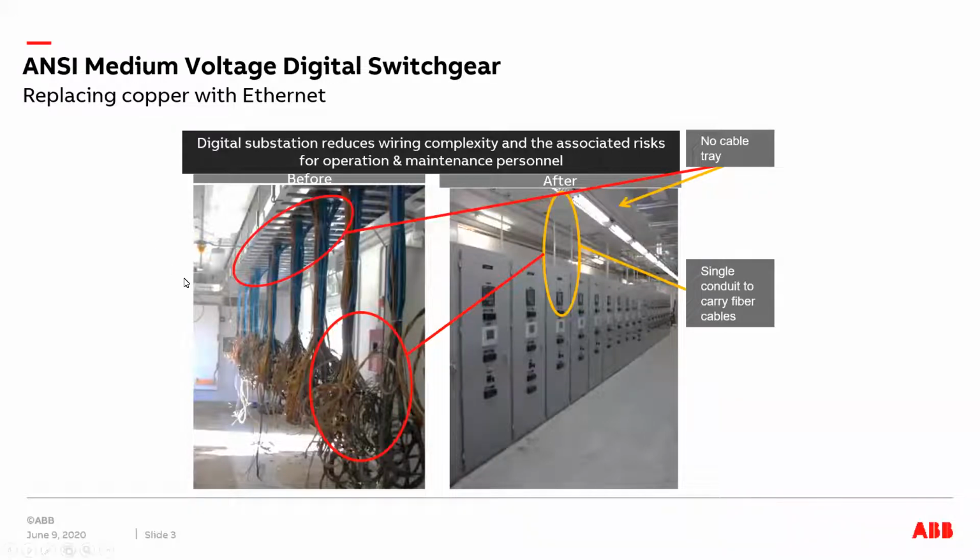So you have some protection scheme, interlocking scheme, ATS scheme, and so on, designed to work between the panels, between the relays of different panels. All those things have to be wired together. So there is a ton of wires drawn through different panels, and there's a dedicated cable tray, as I mentioned before.